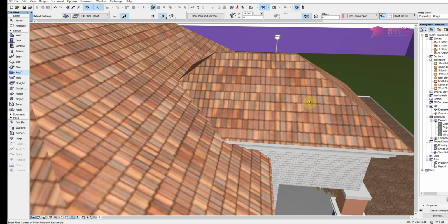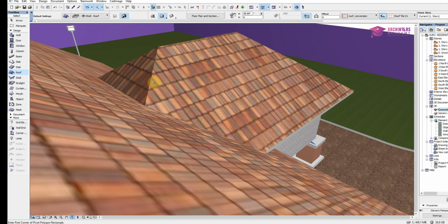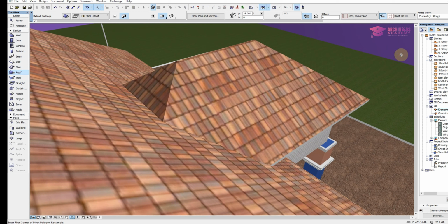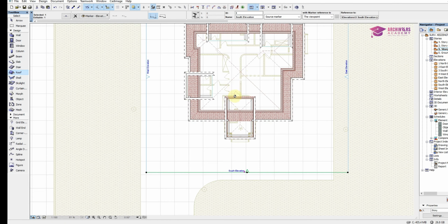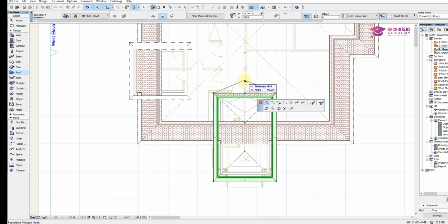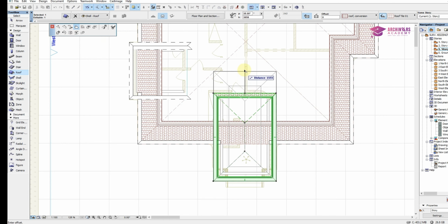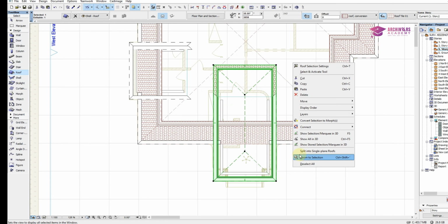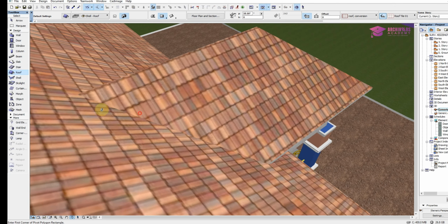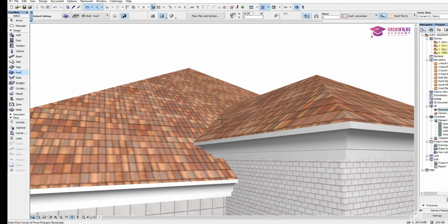But if you also observe, the roofing is not working like this. For a condition like this, we'll have to make the roofing longer. So we'll come over here, highlight the roof and stretch it with offset edge. We're going to stretch it inside more. Let's click show in 3D again. So it's now well placed. You can see this now. This is what you do when you face this kind of challenge.